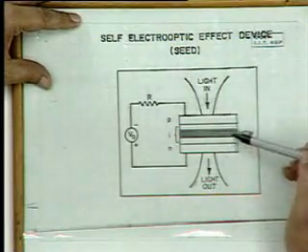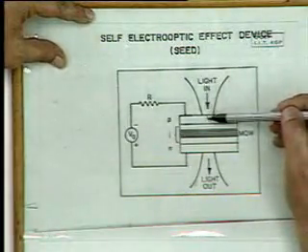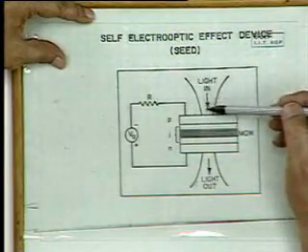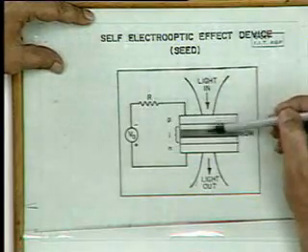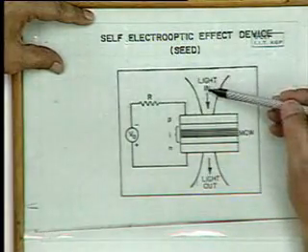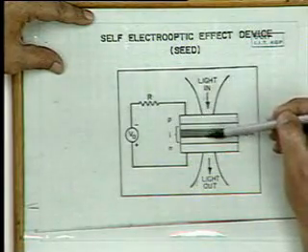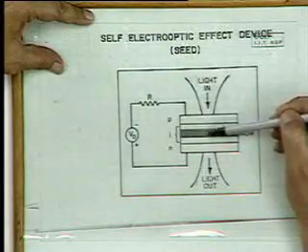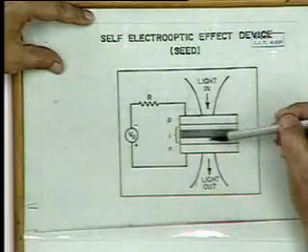For example, you can quite easily understand that suppose you have weak light coming in, and the light is accompanied by an electric field. The electric field is low. It is not having much effect on this MQW structure, and the light is going through. Now, if the light intensity goes above a certain value, what can happen? The electric field due to the light can be large, so it will induce the electro-optic effect. The light itself, that's why it's called self-electro-optic effect, and as a result, the switch will turn off. So it will be like a binary switch.